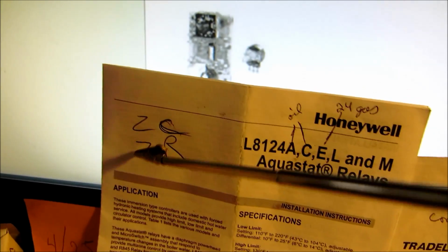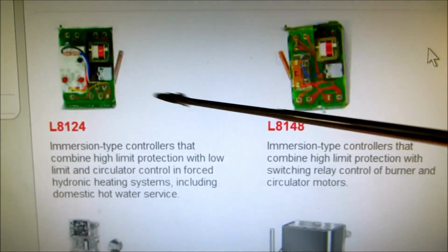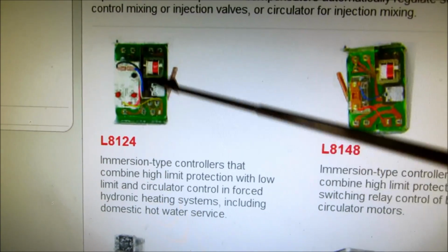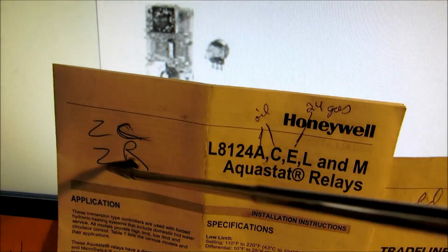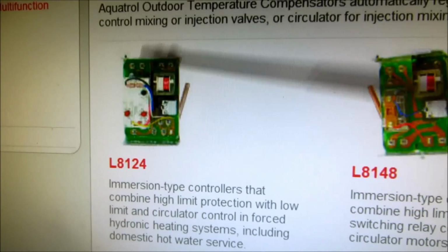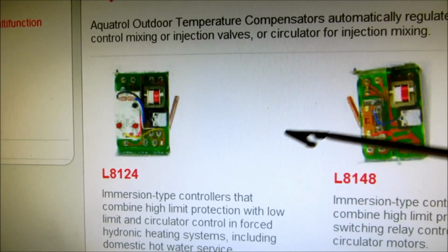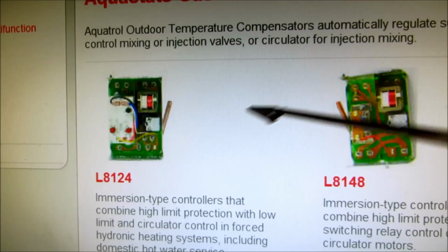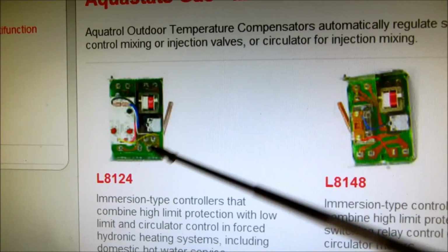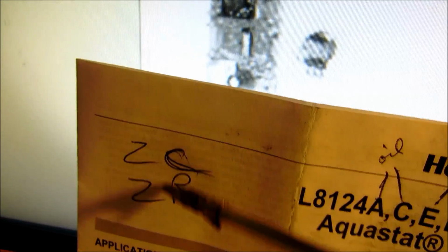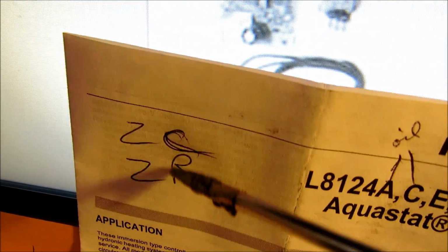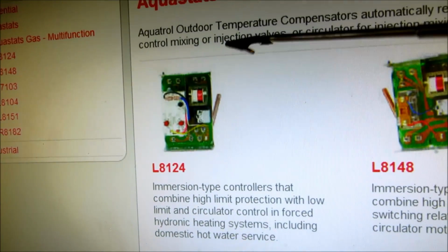And the only thing the ZR does is you send power to that, and then back will fire up the burner on that control. So if you've got this control and you're using it, and you've got like 3 other circulators, you could feed those other circulator controls through that circuit. This one was shut off with the circulator, but after the low limit gets satisfied, this one would fire the burner up with a 110 circuit. That's the only difference with that control.